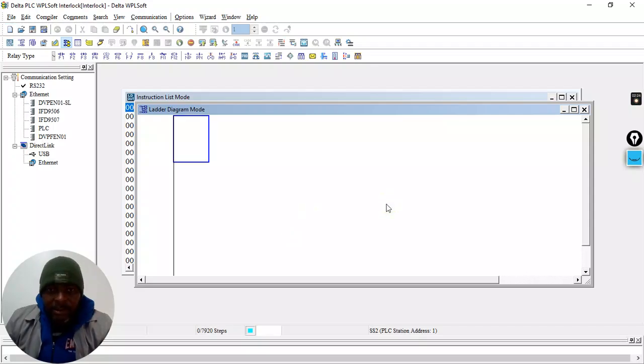Now the concept is basically what we want. Let's look at where an interlock would work. For instance, if there are two processes that cannot happen at the same time, and those processes are controlled by our conductors, we can then program or wire, even mechanically with a mechanical interlock. It's good practice to use both. For security purposes, it's best practice to use both a mechanical and the electrical interlocking, but today we are looking only at the electrical aspect of it. We're going to look at the mechanical one when we look at the practical.